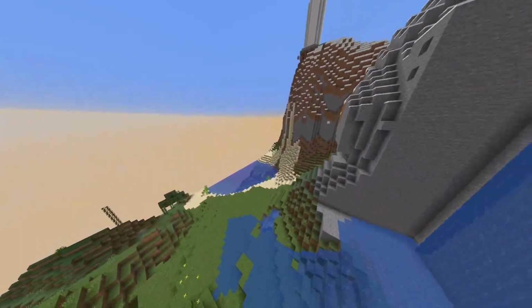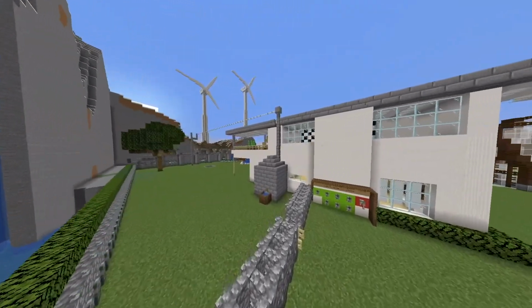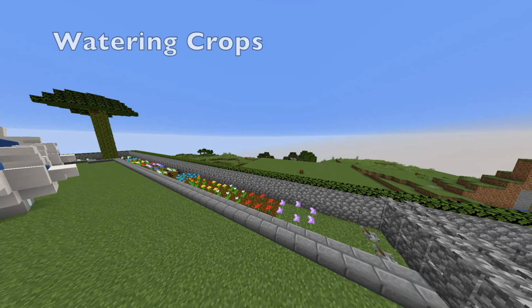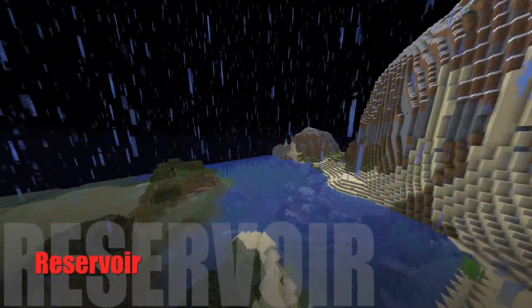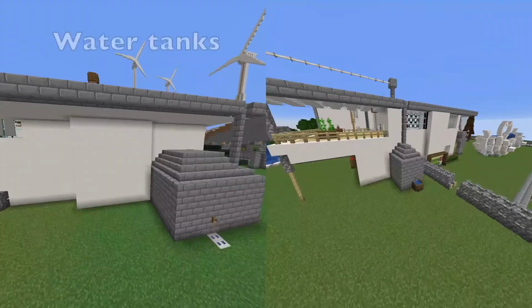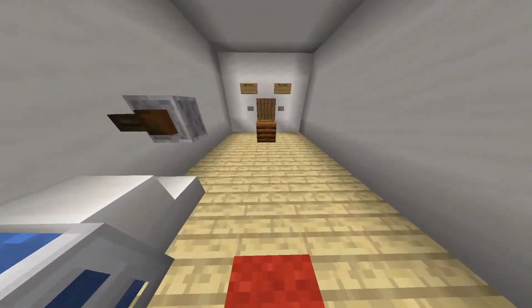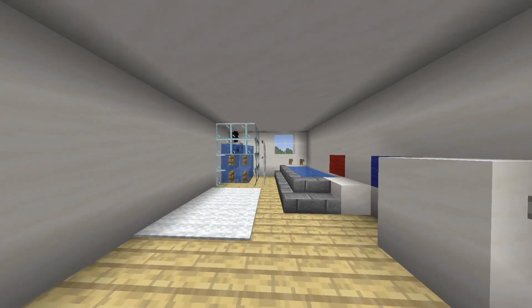Water and waste management. In our home, water and waste management play a critical role in making the home sustainable. Water is the most important part of our house as it is used for drinking, washing, bathing, and watering crops. Water is collected from the rain as well as the reservoir next to our home. Rainwater is collected through gutters from the tilted roof and enters the 2 polyethylene rainwater tanks that hold up to 400 liters of rainwater, which supplies our 2 fountains, toilets, greenhouse water, as well as backyard sprinklers. The reservoir provides water for drinking, the shower, and the taps.